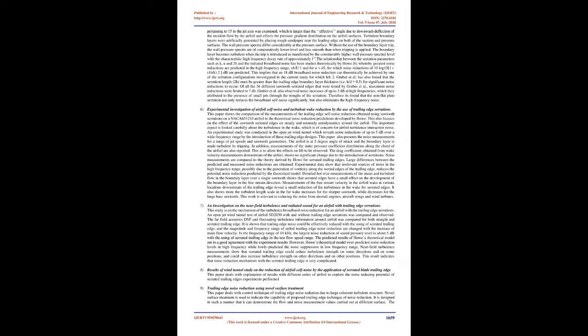The relationship between the serration parameters such as K, U, and 2H and the radiated broadband noise has been studied theoretically by Howe, whereby greatest noise reductions are predicted in the high-frequency range, for which noise reductions of 10 log10(1 + 4H/λ)^2 dB are predicted. This implies that an 18 dB broadband noise reduction can theoretically be achieved by one of the serration configurations investigated in the current study, for which H/λ = 2.